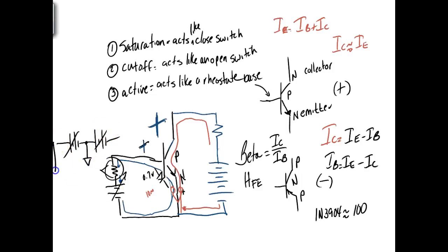So this right here would be the little block labeled what? Plus. This right here would be the little block labeled what? Minus. Well, to do a PNP, I need a plus and a plus. So notice here the negatives are common. That means when you do this lab, you can't use the power supplies on the trainer. You can use one of them, but you're going to have to use an external power supply as the other. Y'all see what I'm talking about?